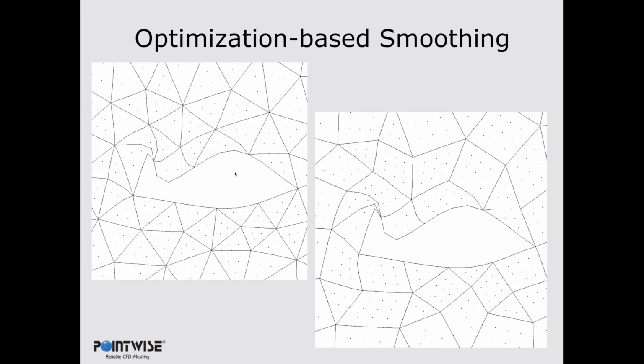So then applying that method to the wavy case that was unsuccessful with the other three methods, the figure on the left is an all triangular mesh, fourth order elements. You can see that it's getting valid elements on the upper side. There's no crossing that's taking place. The figure on the right is a quad dominant mesh. So most of the elements are quads, but there are some triangles. This is actually a triangle here, and there are triangles there. So it's very successful. Again, it's generating valid higher order elements.